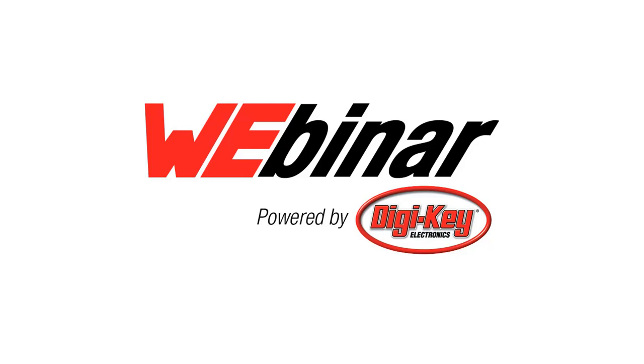Yes, it should be. The ST-USB 4500 really is only involved in the power delivery side. Based on the schematic that was shown in the presentation, only a subset of the pins are used for the power delivery negotiation. We have the CC1 and CC2 pins, as well as VBus and ground. So it's really a subset of signals that we look at for the power delivery.